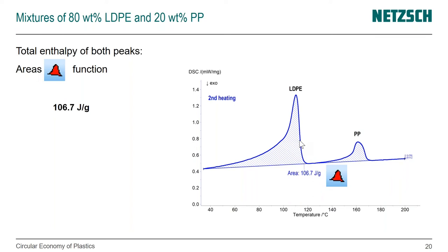You normalize your measurements based on the weight percentage. And if you don't know, another way to determine the weight percentages of fillers like glass fibers and mineral or talcum, obviously, is also thermogravimetric analysis, where you can literally just burn off the organic matrix and you can obtain the weight of the mineral or inorganic additive or filler. Yeah.